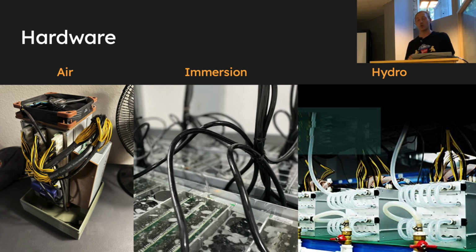And here you don't have to cool all the other components. You also don't have to deal with the dielectric fluid, which can be expensive. It can be toxic in some manners. It's heavier. So a lot of people have conflicting opinions. Some people don't like immersion, some people do. There are trade-offs to each. In terms of heat transfer, both of them, the fluids are much better at transferring this energy over distances. That's because they have that high specific heat capacity, which means it takes more energy to change the temperature of it, right?